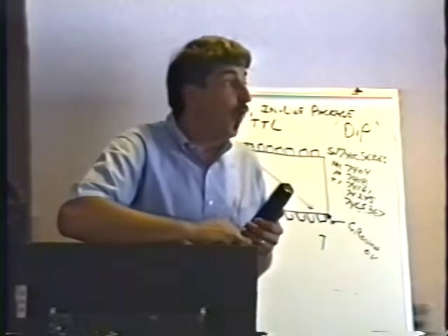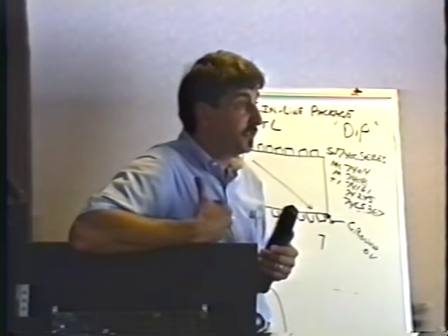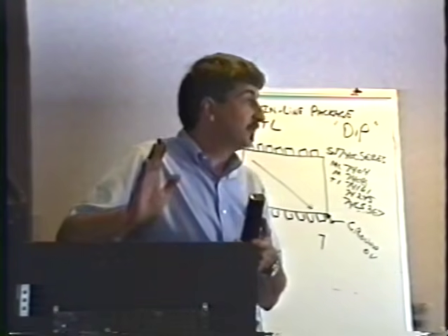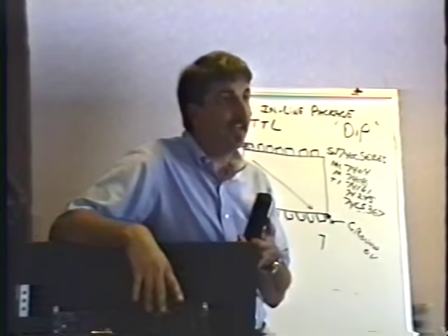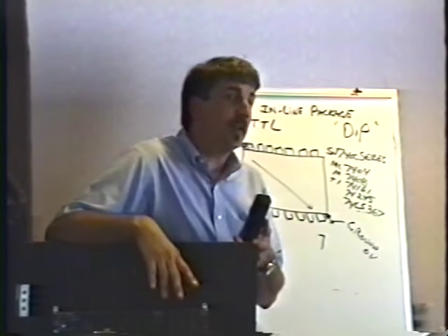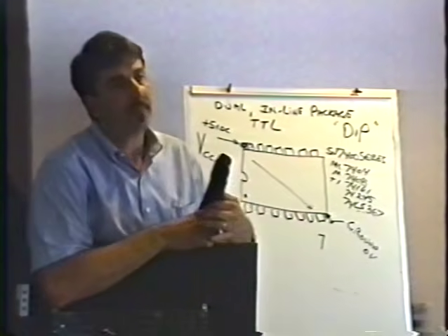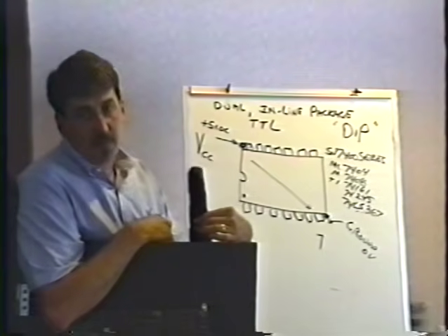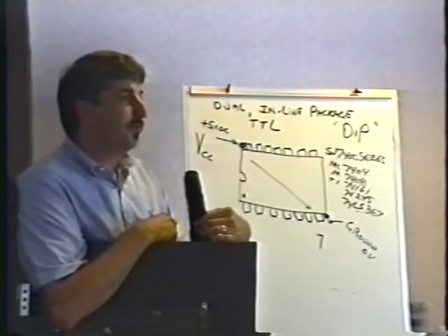Naturally, you always want to eliminate your power supply as a cause of this problem. You want to make sure that you adjust the 5 volts so that all that is perfect before you do anything to the board. And as a matter of fact, and this is pretty important, so try to remember this, sometimes you'll have a weird power supply problem where the 5 volts really does seem perfectly okay.